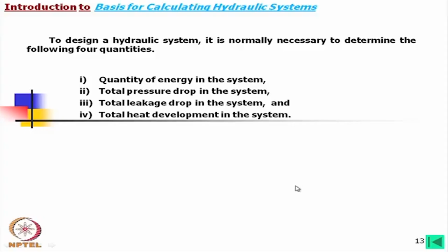Now, a hydraulic motor of that size can deliver maybe 20 kilowatt, where the electric fan is only 100 watt. The hydraulic motor of the same envelope size can deliver 20 kilowatt. So, that is why in many places it is very convenient to use such a system, although overall, if we consider the reservoir and so on, it will be of huge size.